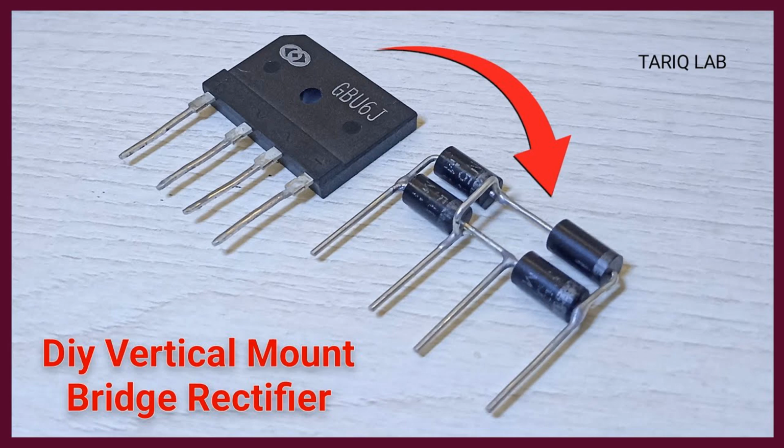Emergency backup systems. Industrial automation systems often incorporate backup power systems, such as uninterruptible power supplies, UPS, or battery backup systems, to ensure uninterrupted operation during power outages or voltage fluctuations. Bridge rectifiers may be used in the rectification and charging circuits of these backup power systems to convert AC power into DC power for charging backup batteries and providing emergency power to critical equipment.